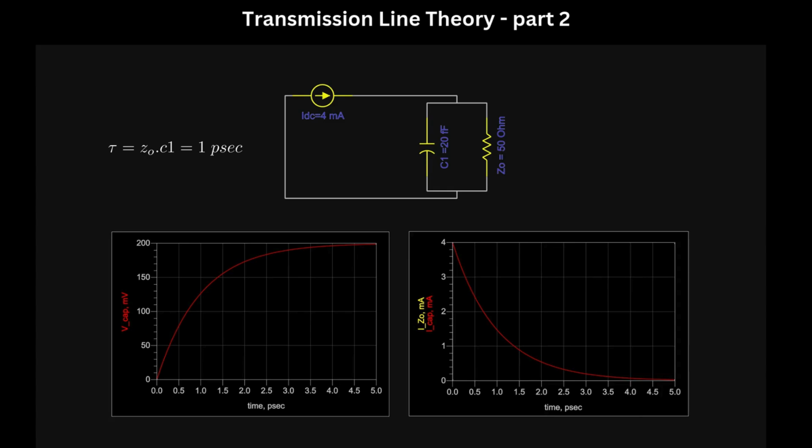Since the sum of two currents is constant, the current entering the resistance is increasing exponentially till reaching the value of the constant current source, when the current in the cap reaches 0. Notice that the resistance Z0 contains all the remaining sections.